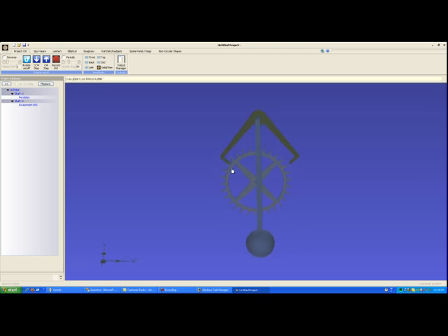Typically, to attach a pendulum to a clock, you'll hang it on a pivot. Some use a thin piece of springy metal. Others will make a circular holder with a sharp point on it and hang it on a post. What comes off of the pawl will then be a lever with a wire on it, and the wire gets wrapped around the pendulum so that it's got some looseness to it. This helps to cut any vibration from the pendulum from feeding back into the system. But I can probably show you a photo of that later on.